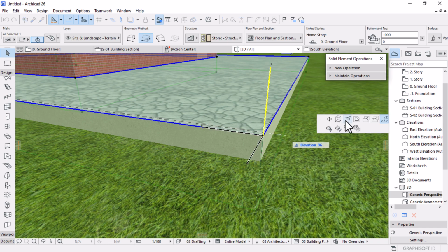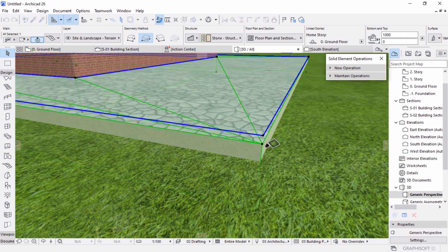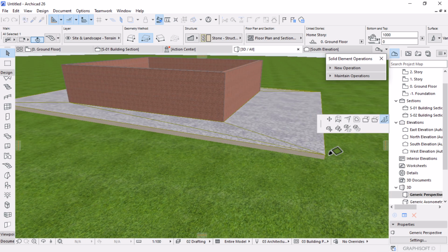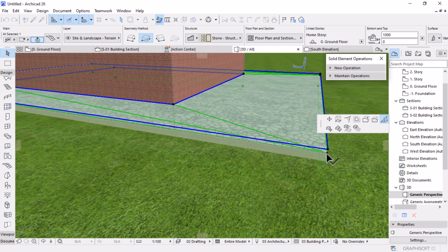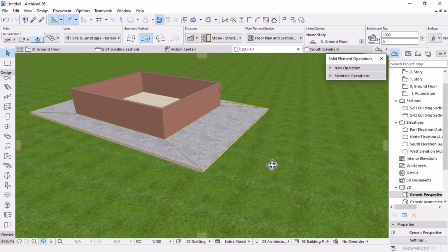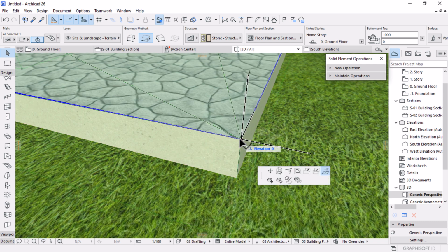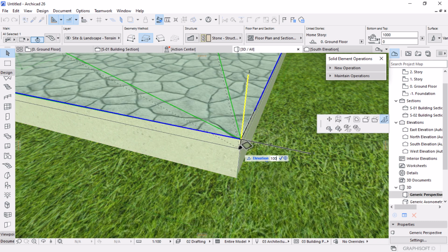Let's pick the point and then activate the elevate mesh, go down by 100, do the same to that edge. I will reference with this, and then do the same to the other side, reference with this. Let's orbit by hitting O on your keyboard to drop this also by 100.